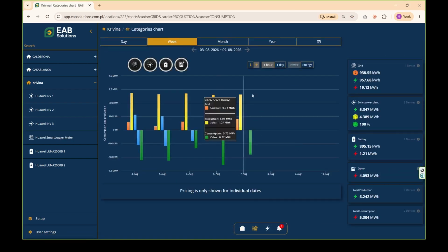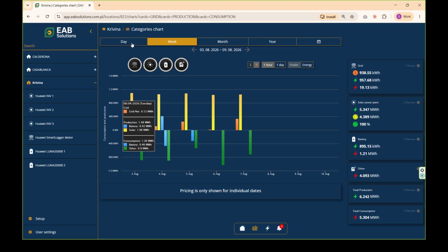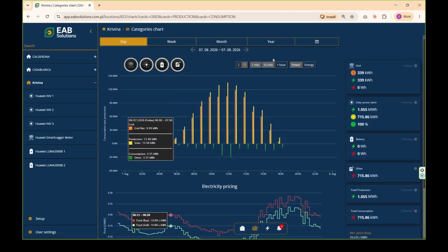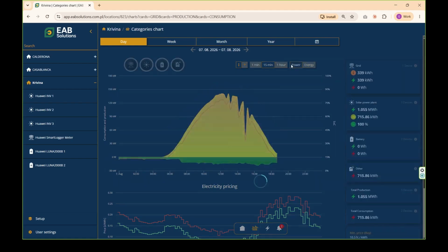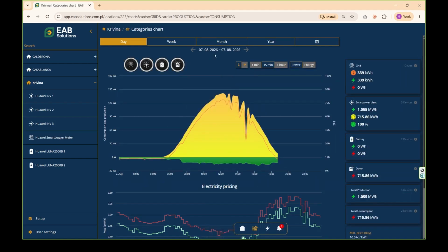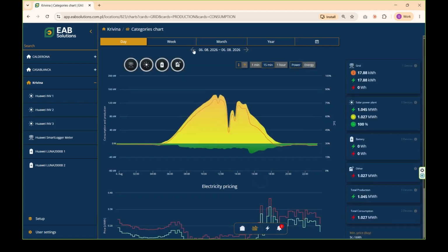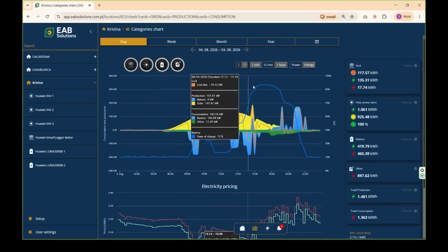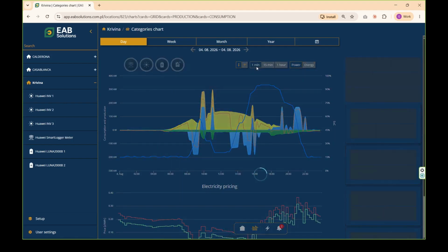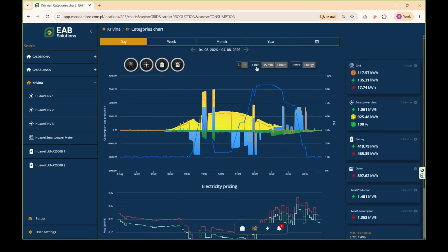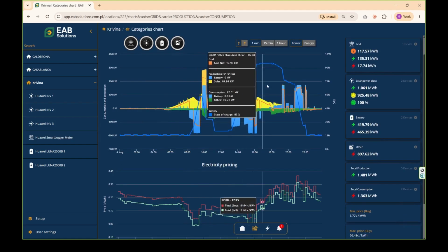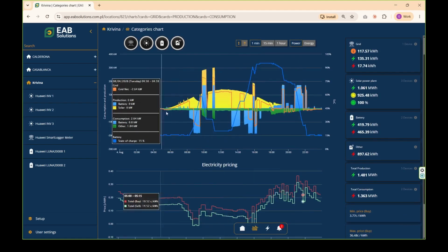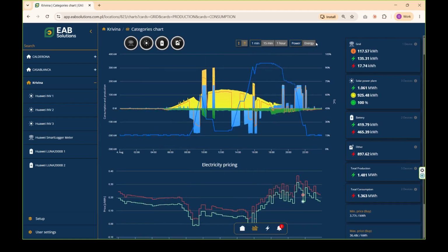Here, as we've shown, you can equally put on a weekly view all the charts that were shown before daily, charts of the behavior. Before, we were looking at the charts at power level. We had power charts at 15 minutes, which are these we see on screen. If we want finer detail, our EMS always records everything at 1 minute. It records at 1 minute, even though it monitors at 1 second. And we can go down to 1 minute, which is how the data is recorded in order to do diagnostics and to know roughly what the behavior has been, both in power and in energy.